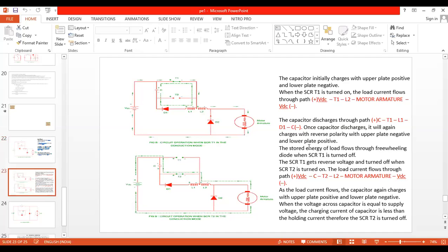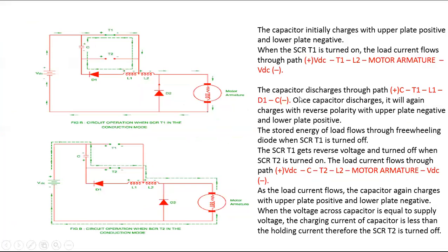I will make it maximum for you people. You can see this circuit, but in the examination, two different circuits you have to show. Here in the animation, it should be plus and it should be minus, because current is entering this terminal first. So when the supply is on, current flows to T1 and to the motor. The motor rotates and accelerates. That's case 1.